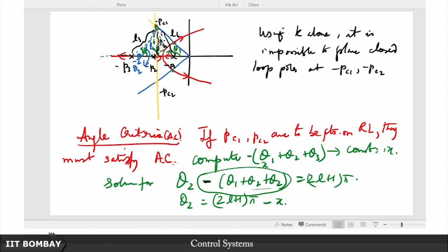In general, of course, at this point it might seem like I am doing a lot of hand waving, but when we actually deal with real numbers, you will see that it's true, that this product L1, L2, L3 has increased manifold times. So even if it gets divided by this L, this L, the length of the line from the newly introduced 0 to PC1, might actually be almost equal to one of these L1, L2, L3. There are still the other two factors remaining, but these have increased so much that now the product of any two of these factors is greater than the erstwhile product of all three factors in the uncompensated system. You follow?